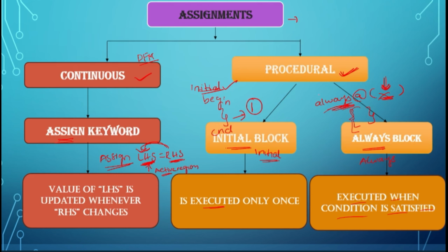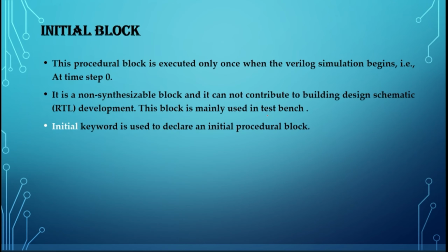But the only rule for the assign statement is that the LHS should always be of wire data type, but it should not be reg. Okay, so these are the assignments that you will be seeing in Verilog. One is continuous and one is procedural.